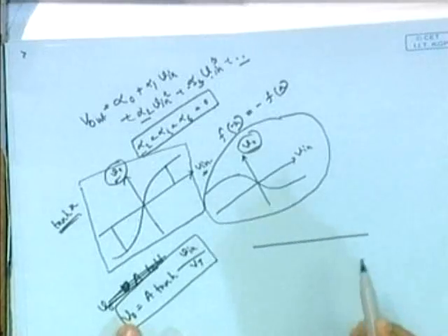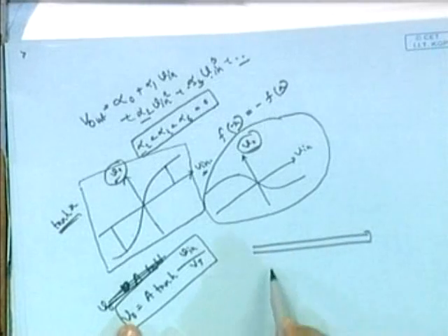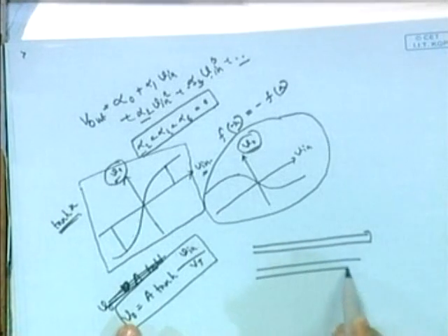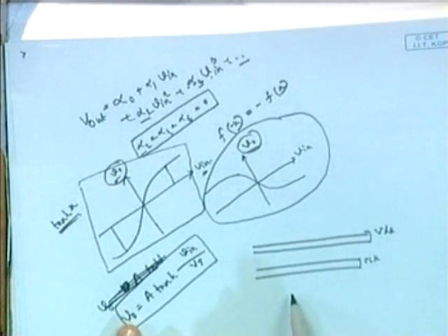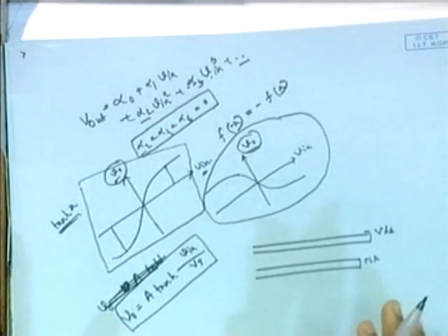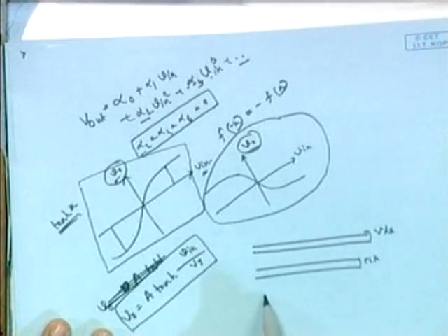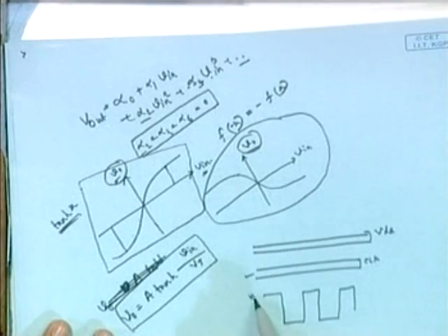And also suppose you are drawing this VDD line in your layout, and very near to that there is a clock. This is the clock line, this is your supply. And as you know, all digital circuits are most noisy, because they are always switching from 0 to VDD. There is a sharp change in inputs and outputs of all digital circuits. So the clock is also the main source of induced noise. The clock waveform is like that. It is going from 0 to VDD.